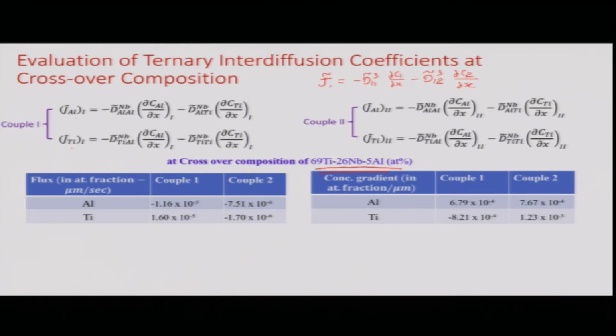We can also express the concentrations in terms of atom fractions. So if we express concentrations in terms of atom fractions, we can write C1 Vm is equal to x1, that is the atom fraction or mole fraction, and so x1 would be C1 over Vm. So if we divide both sides by Vm, we can express this equation in terms of gradient of mole fractions